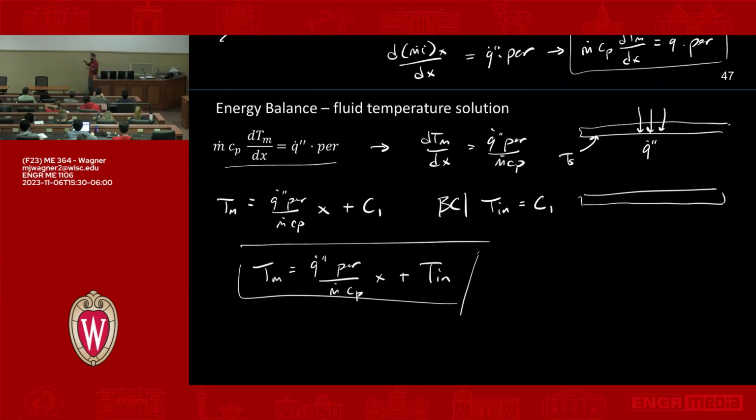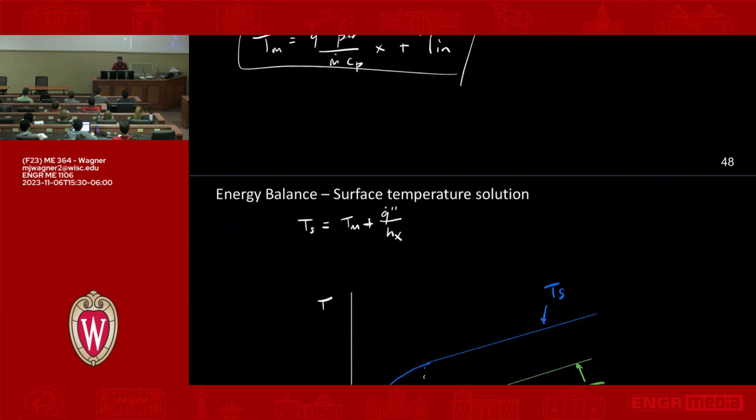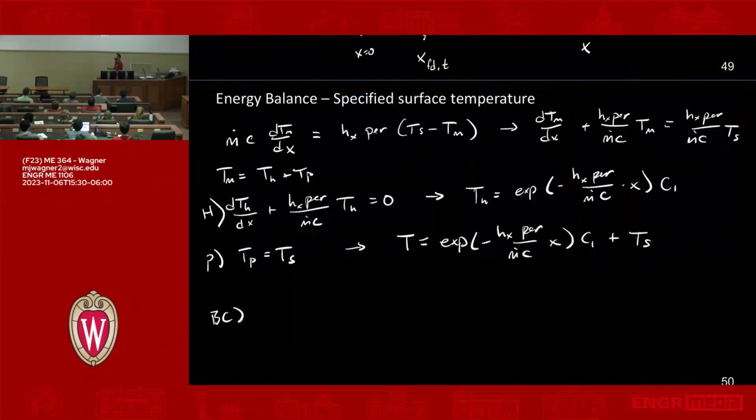So I'm saying, I have this pipe. I've wrapped the pipe in resistive wire, and I'm putting voltage on that. There's a constant heat flux as a function of position, right? That's a constant specified heat flux. That's one situation. In this situation, now we're thinking about a pipe, and I'm boiling water on the outside of the pipe at a constant surface temperature, and it's a different situation. So with that in mind, it's a constant Ts here, different solution. Good question. Okay, so the boundary condition, remember, has to be in terms of the thing we're modeling, Tm.